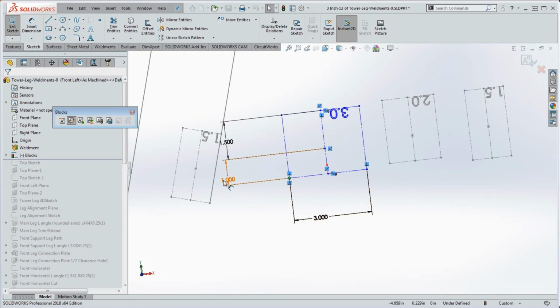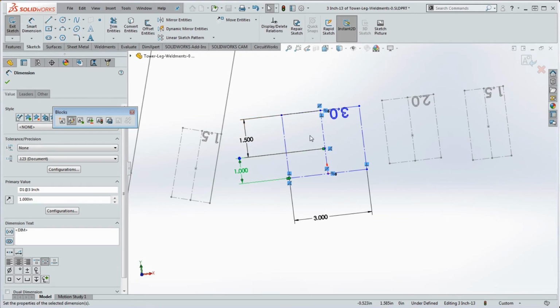So we have 3 inches on the front. We have 1 inch, which defines where that alignment point is going to go and where the hole location is going to go ultimately. It's going to go right on top of that point. Now, if we need to, like in connection blocks, we have a second point back here, which is going to be 1.5 inches. So these are kind of arbitrary dimensions, what I measured out in the field. But if all of a sudden something comes along and you need to change that, and it needs to be 1 1/4 instead of 1 inch or 1.5, imagine this. Since I have hundreds of these sketch blocks throughout my model, throughout the 4 different legs and the top of the tower, if I just change one sketch block, it all changes and all updates. What could quite literally take an hour or more in a regular model now can take a matter of seconds. So, you can take off early for the weekend if you want to do that.